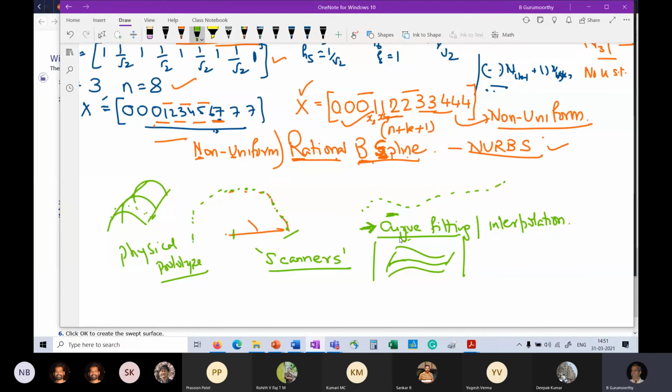X coordinate comes from the location of the light on this gantry. And therefore, what would take days to pick points on a curve, now I can get in less than a minute. Now, even more powerful is that if I don't have a point source, but I have a sheet or a line of light, then, of course, it is much faster. Then I'm scanning the entire surface in one go and getting points on the surface.